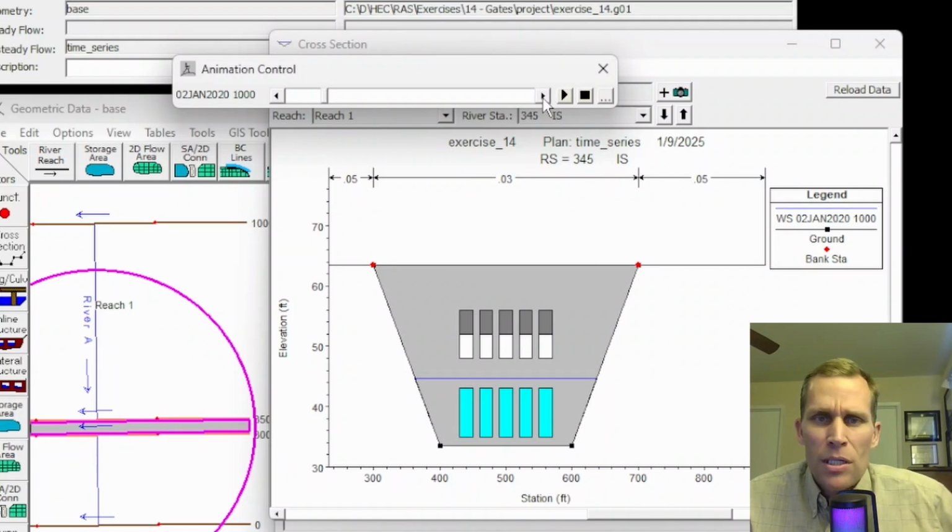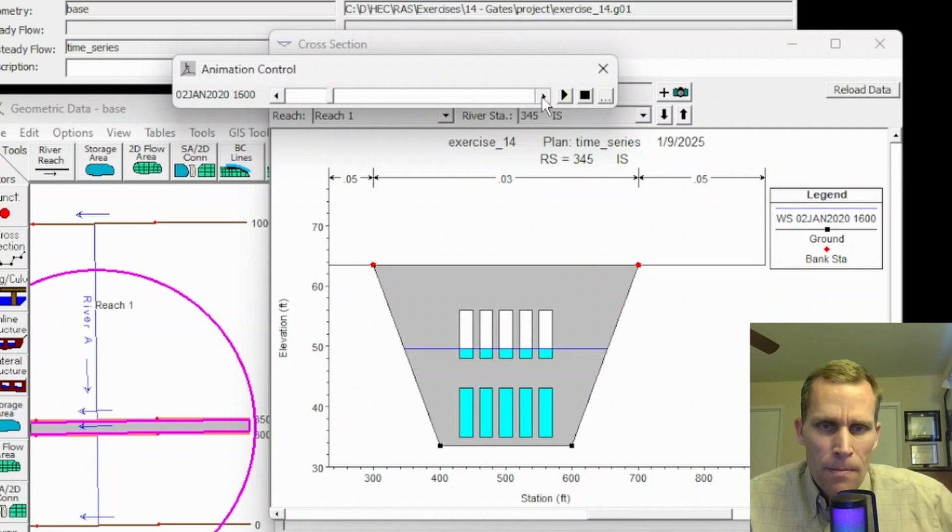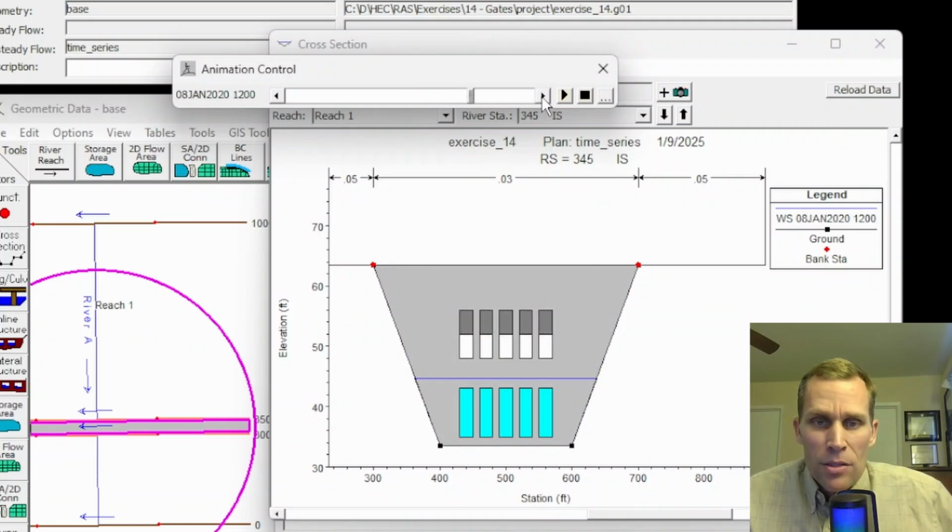So we're approaching the 15,000 CFS mark. Okay. And then the upper gate group opened up 100%. That's 15,000 CFS. And then right there is 20,000 CFS. And then that's 25,000 CFS. Now it's going to slowly decrease in flow, and also the water surface elevation is going to slowly decrease. And then pretty soon, in about a day, we're going to see the top gate group go down 50%, which is right about there. Yep, there it went. Cool. So now it's just a 10,000 CFS flow for the rest of the simulation.